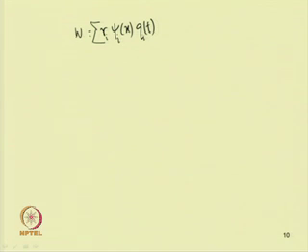So, by taking different modes, one can write the transverse displacement equal to R I into psi I x into q I t, where I equal to 1 to infinity. But in the actual case, as the higher modes will not be useful for our study, one can limit the number of modes to a few lower terms. So, it can be written as I equal to 1 to n, R I psi I x into q I t.